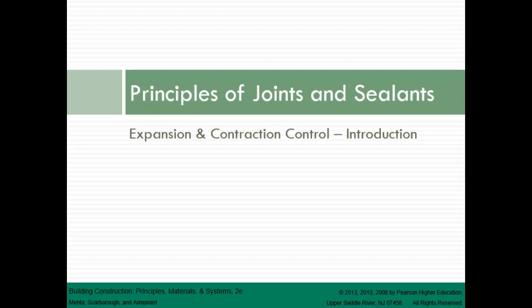Building joints result from our need to work with materials that can be easily and efficiently fabricated, transported, and assembled on site. The joints also allow field adjustments in assemblies during construction. Additionally, visible connections resulting from the joints provide an opportunity to develop ideas of scale, pattern, color, texture, and so on building planes and surfaces.